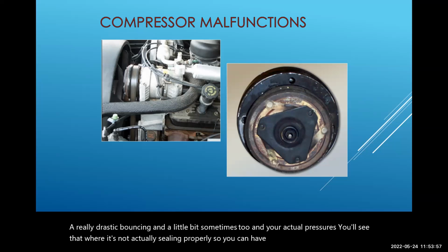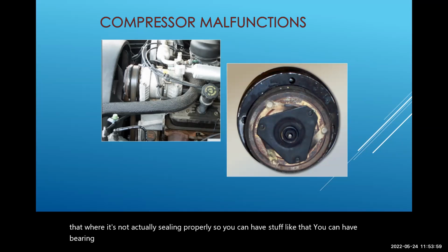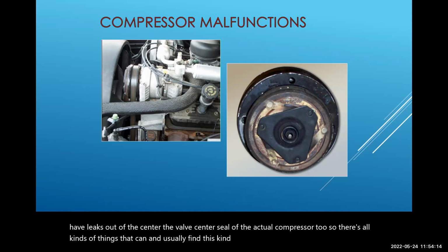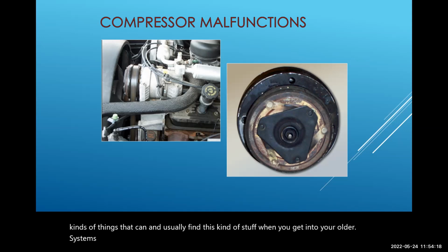You can have bearing noises. You can have leaks from the hoses or the head assembly. You can actually have leaks out of the center valve seal of the compressor too. You usually find this kind of stuff when you get into your older systems. But keep an eye out, and always do your leak checks before you go too much farther. The correct charge will show you things like this.